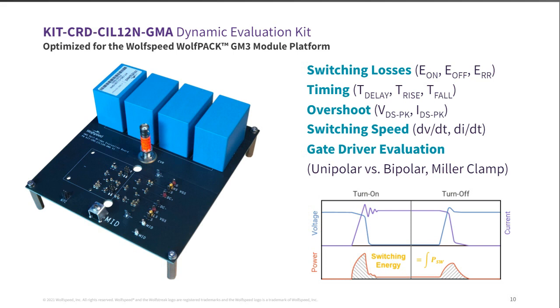What this dynamic evaluation kit is for is exactly what the name suggests. This would be for clamped inductive load or double pulse testing, so you can evaluate the module.